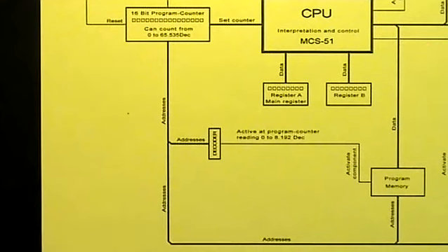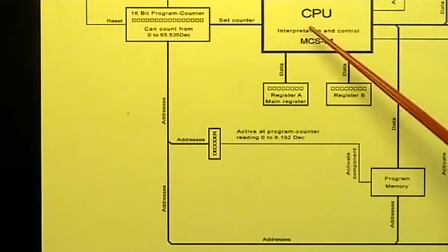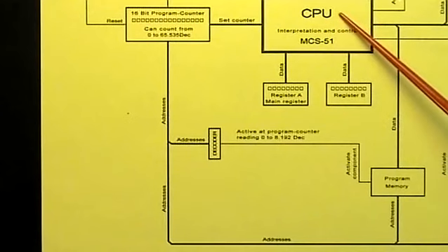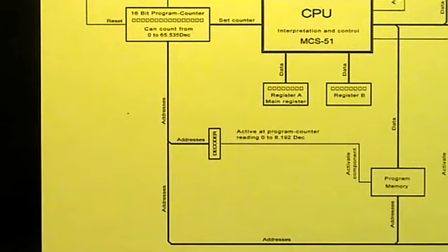The control center of a microcontroller is the CPU, the Central Processing Unit. Here, in the demonstration example of the running light, the 8-bit data content at address 0 is 00000010 binary.